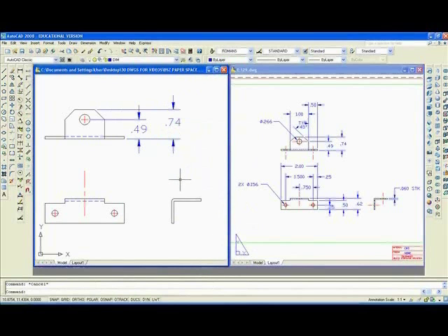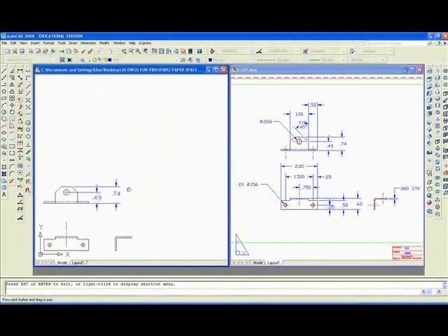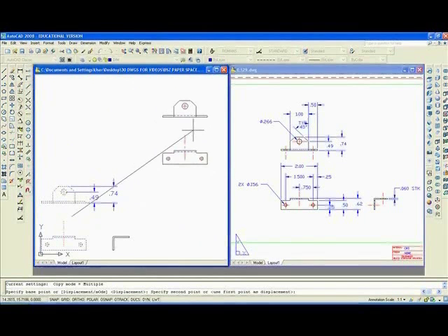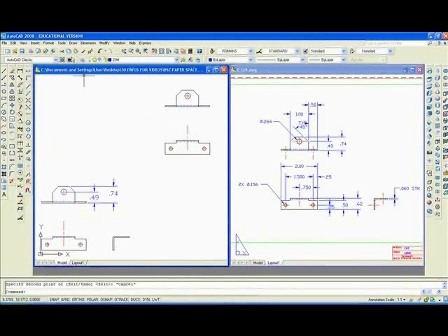I want to get on to the solid model. I'm going to zoom real time, shrink it down, pan, move it over to the lower left, and then we'll want to copy the front and the top view. Move them to the upper right. Hit escape.